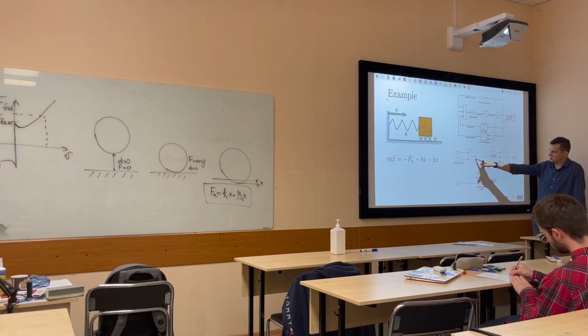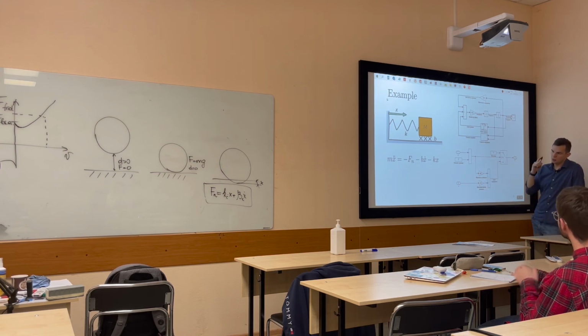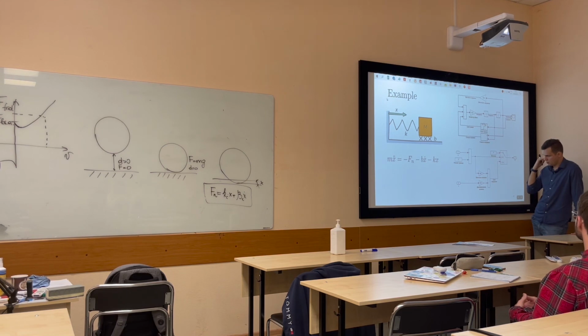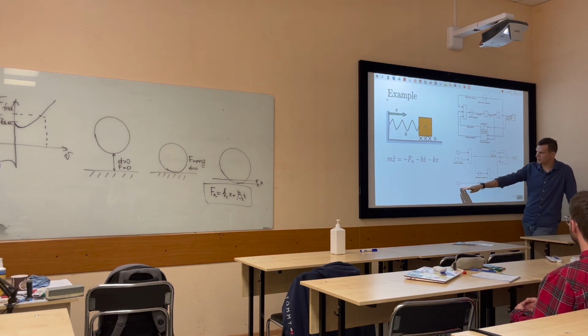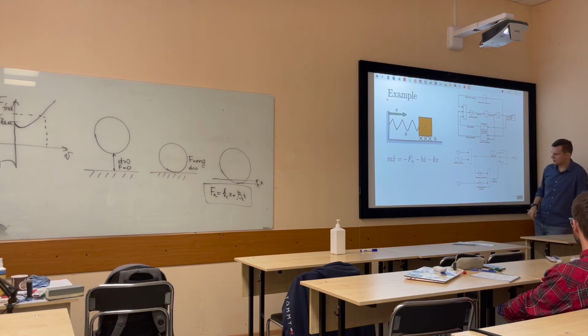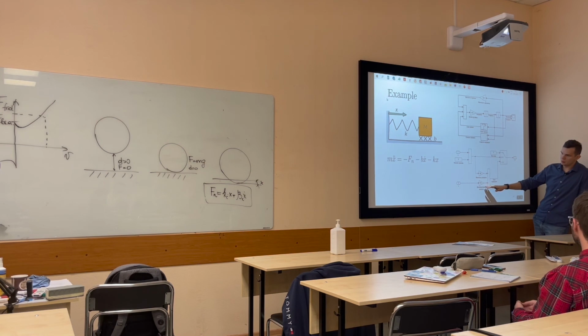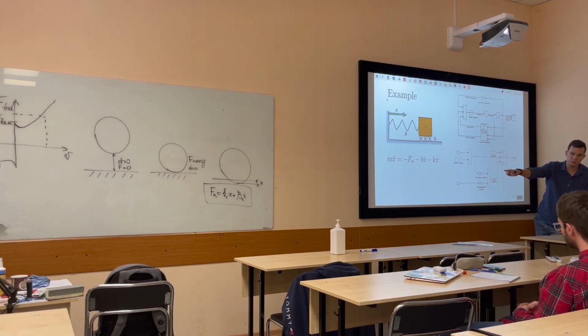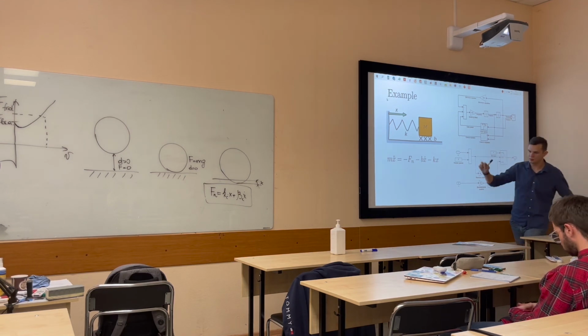you can take this penetration and multiply it with the contact stiffness coefficient. You can take a time derivative here, x dot, multiply it with the contact damping, to calculate the force according to the equation, and you get the force that needs to be applied there.